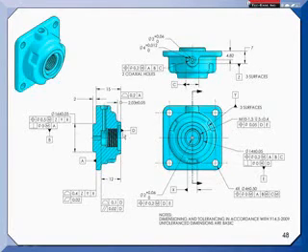But then I've added this datum feature D, which is where the other part comes in. So this surface is constraining 3 degrees of freedom on the mating part. And I wanted to be able to control where this surface is quite tightly to this surface because of that gap we're trying to maintain. I wanted to have a direct relationship there. So I did make this datum feature D so I could put the profile and parallelism on this surface back to D.